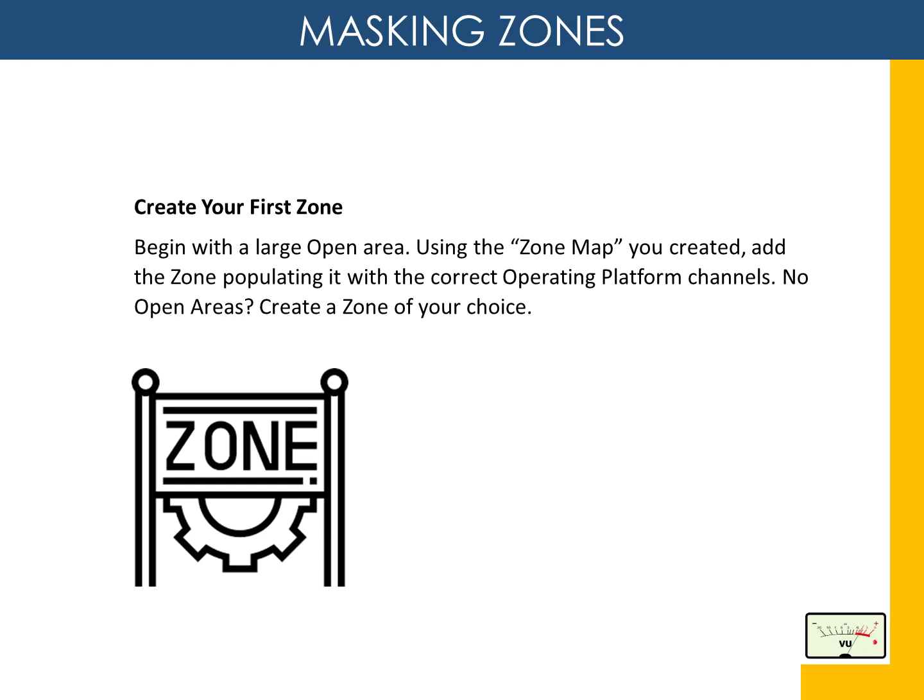If available, always start with a large open area. Once the tuning in the open space is completed, you have likely tuned the majority of the project or floor where the sound masking has been installed. Open areas are much easier to hear and to get a sense of where you need to be with regard to levels and contour. No doubt that trial and error is the rule of the day.